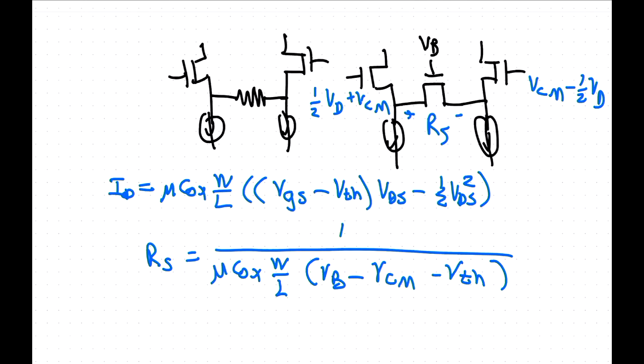No, because it never happens, because you define the drain in an NMOS transistor as the terminal with the highest voltage. If you're tying the bulk to something which is not your negative power supply, it is still technically true that the terminal with the highest voltage is the drain.